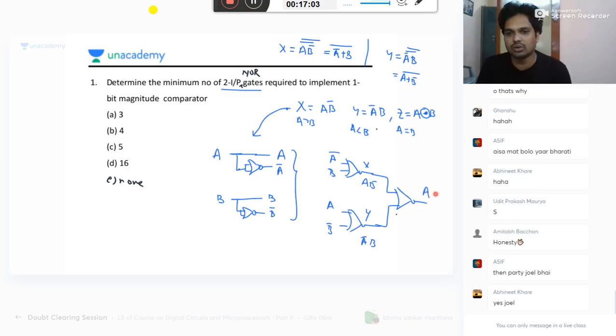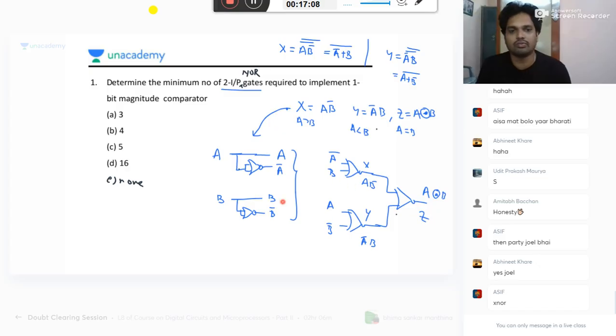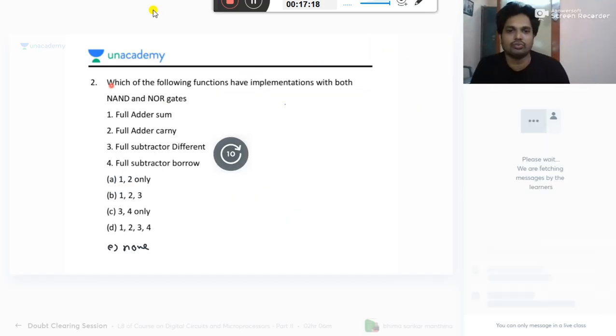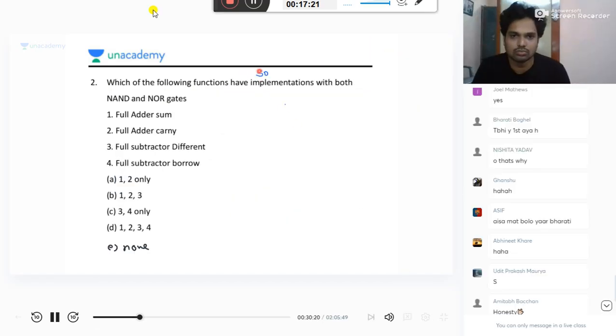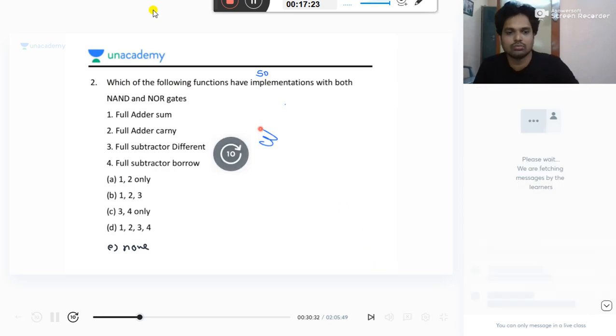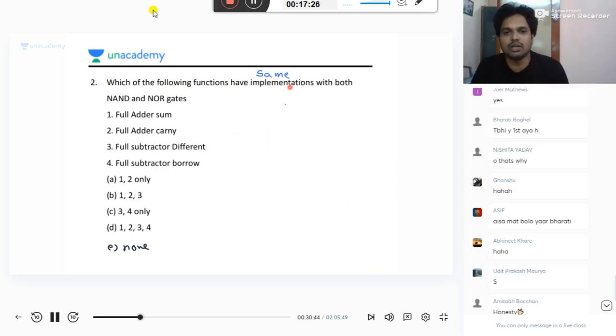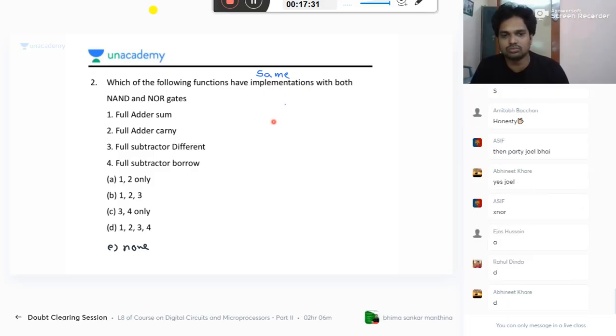This question, one simple way to solve it is, listen, toggle mode you can say. Two different ways I will tell you. Initially you assume this is 0 and 1. J, Q bar, assuming initially cleared 0. Then clocked 6 clock pulses. The sequence of output is this. So apply the first clock pulse. This is the condition now. In the first clock pulse when you apply, what is the output you get? What is the input to the JK flip-flop? 1 1. You get 1 0. This 0 will go here.